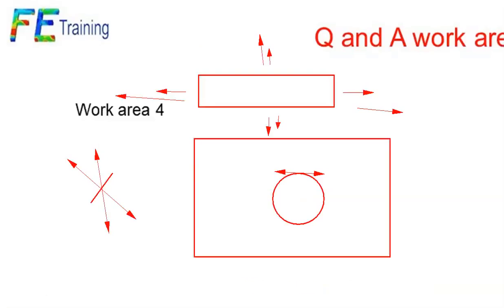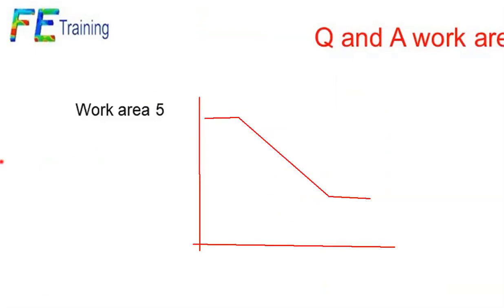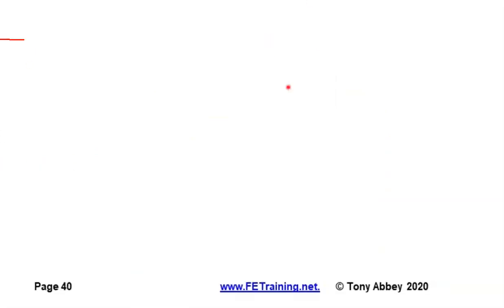So the question is, as soon as I move my thing over here, it's like whack-a-mole, it bounces around all over the place. That last slope, we can either assume it's horizontal, assume it's a continuation of the main slope, or we have some data to tell us what that slope is. We can make some assumptions, such as using half the slope. Remember, that's a very high cycle, 10 to the 9 cycles, because it's a log scale.